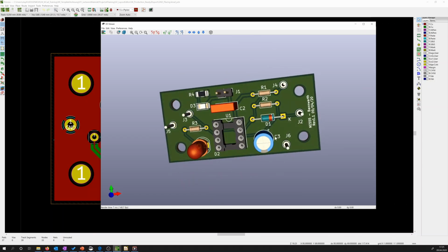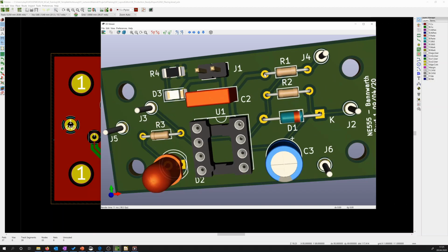So this looks fine. We see the traces, the distance, and the silk layer, and you also see that this is the pad, where we can see the copper, which is plated in gold in this case, and here you see the opening for the soldering, and here it's covered by the solder mask. So you see, it might be hard to have a connection to this signal or to this signal without these test points, and also it might be hard to have a ground connection without these test points.